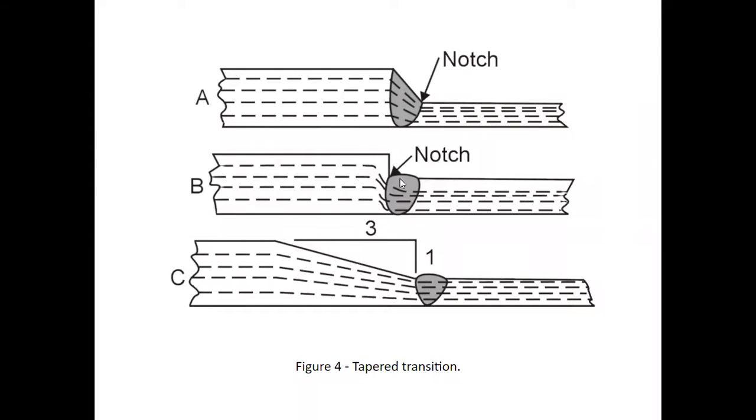This one here, we can see there is no attempt to bevel this back, no attempt to make it flow with welding. It's just a single bevel here. They threw a ton of weld in it, and they have this hard transition. So a couple options here. We can taper it back. See, here's taper back on a 3-to-1 ratio. This gives us stress lines nice flow opportunities. There's no hard bunching, no hard transitions. There is a bit of a harder transition right here, but I think that's just due to the animation.